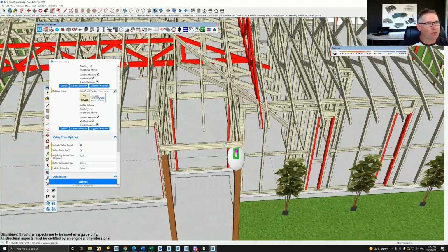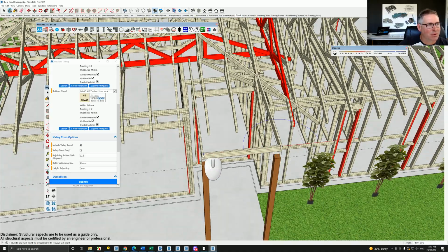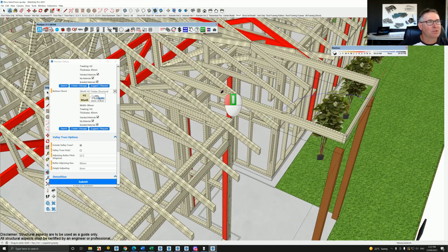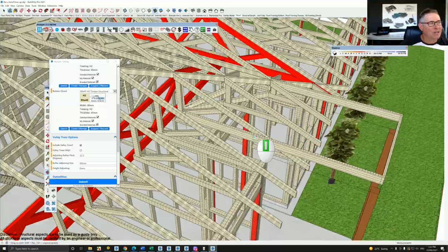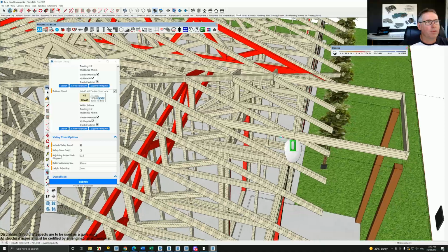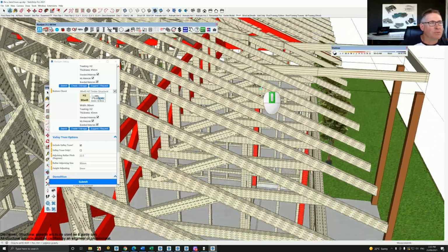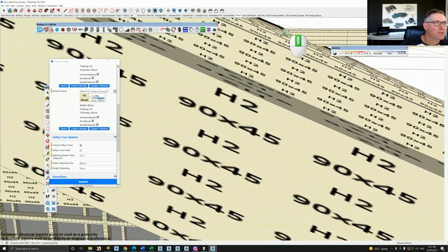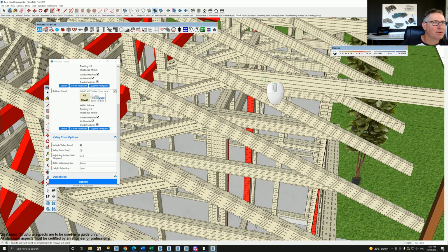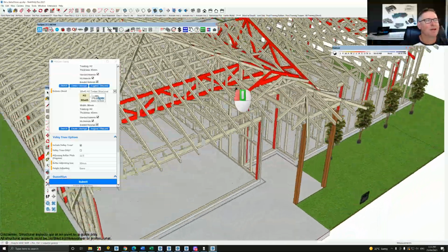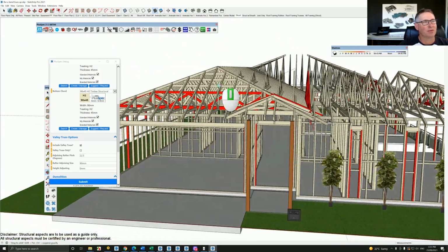And now I have my roof pitching in there. I have one more to do, and the reason why I put these beams in is so I could actually see where I'm going to pitch my roof from. And I'm going to go through until I get to... Now I don't actually need a girder here. We can edit trusses later if we want to. I probably should have drawn a tape measure line across here first. So I really want to go to, say, roughly 99 inside. I eyeballed it, but I should have got this correct. The underside of that, you'll notice. Right, and now I actually have my trusses drawn the way that I actually want them to be.